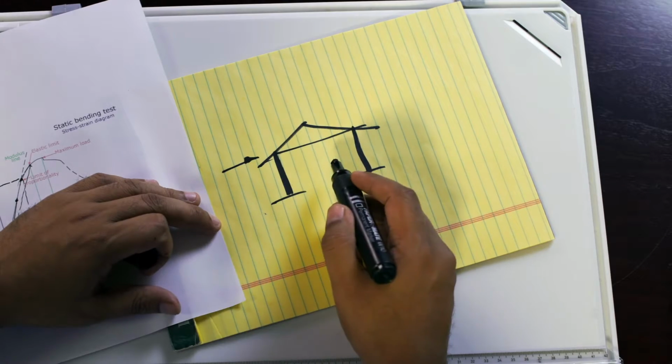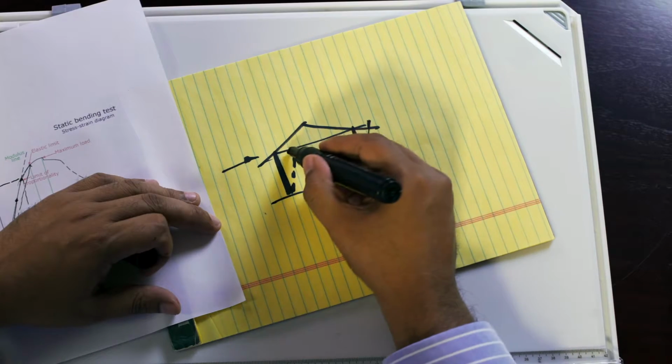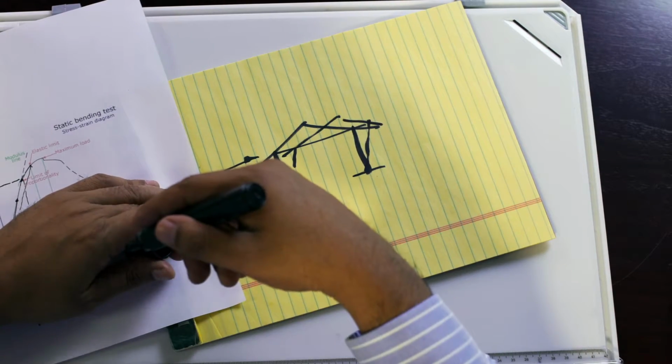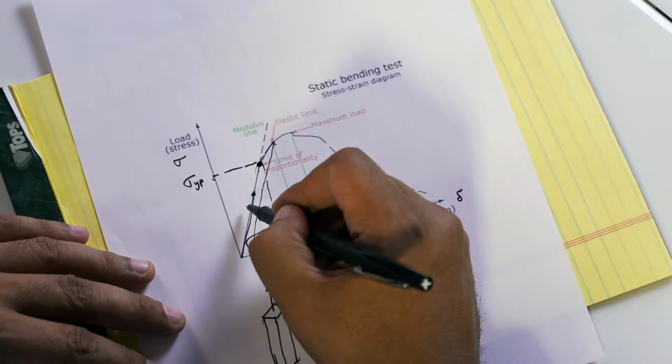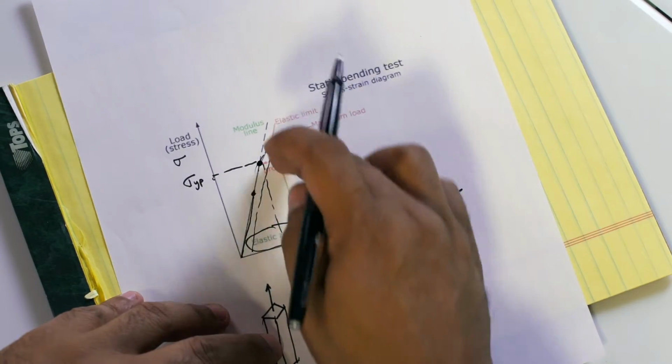Can you imagine if you're designing a building and let's take a simple example of a house. Here's my simple house, and it gets hit by a windstorm, and the building deflects, and it doesn't go back. Who wants to live in a house like that? So that can't happen. So we don't allow that to happen. And the way that we don't allow that to happen is we make sure that we never exceed that yield point. Because even though we have all this extra strength, we don't make use of it. We don't take advantage of it. We are only interested in having the structure return back to its original location.